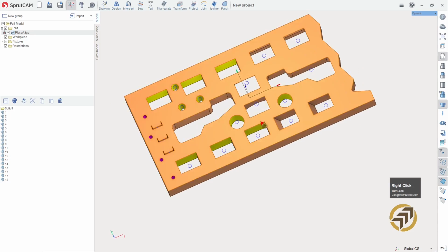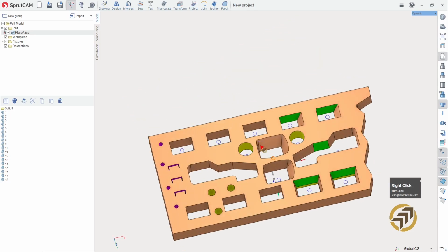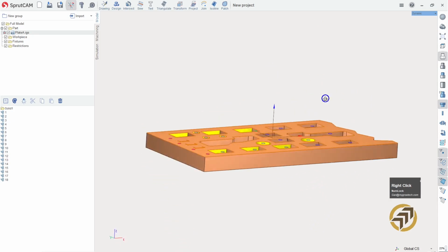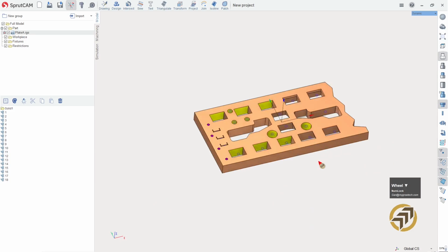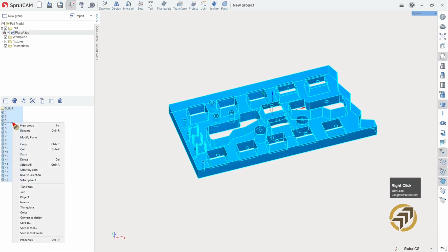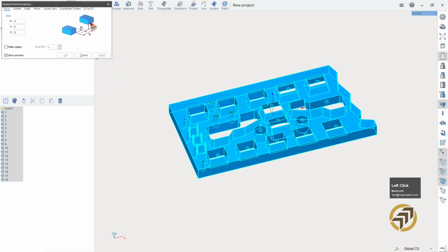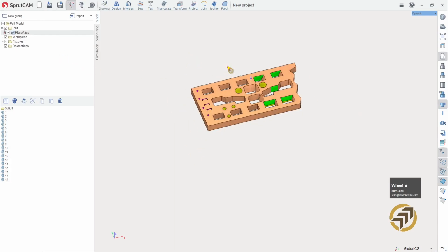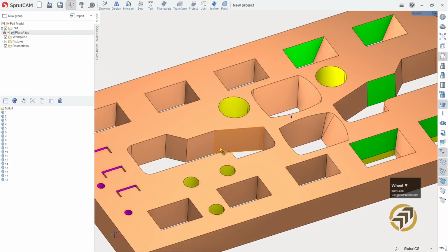Before that, because this side is tapered, it is good practice to put the taper side on top. So I need to press Control A, then make the transform, rotate the part. I want 0 and OK. And this will be the part that we're going to machine.